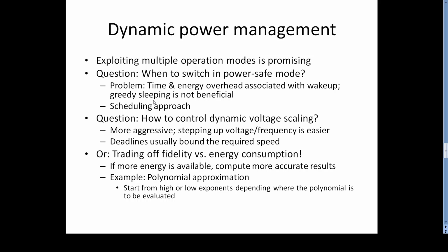Actually, greedy sleeping mode is also not beneficial because it takes more time to activate, and energy also to wake up. That is the problem. So there is time and energy overhead associated with waking up the node if it is in deep sleep mode. Another option we can use is the scheduling approach.